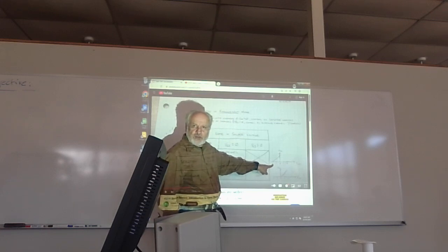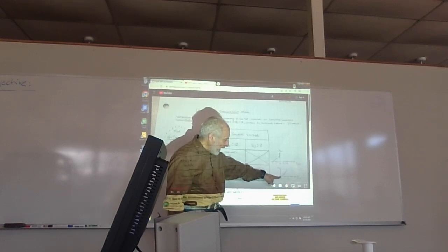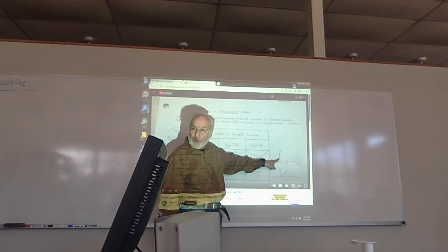Reverse. That's the transconductance, isn't it? Right? This is VGS versus ID. And if you notice here, this is what we're going to be doing in the lab. So we're using a depletion type device. Enhancement, on the other hand, the more VGS you have, the more ID you will have. You with me so far?